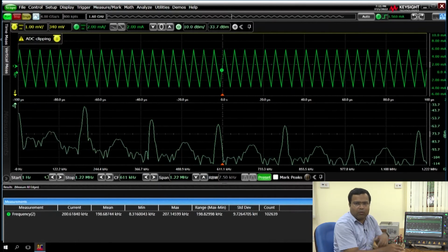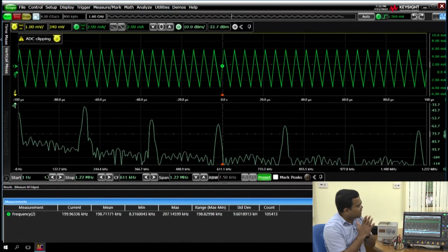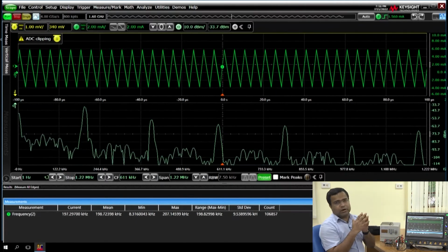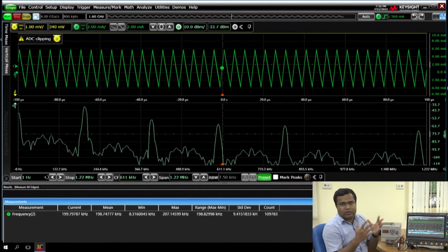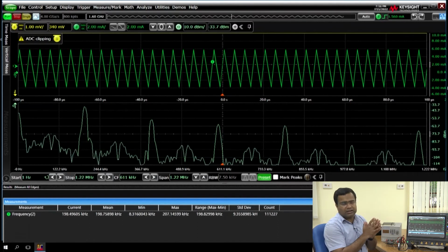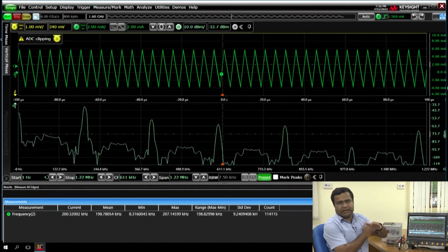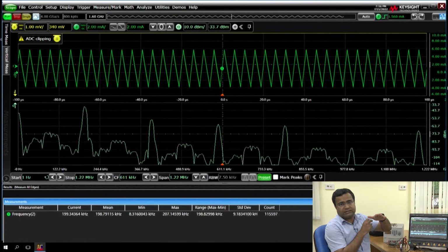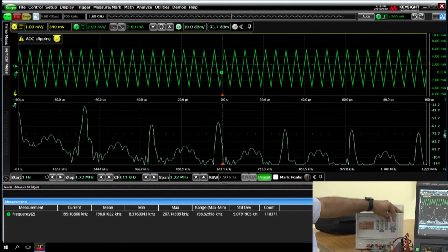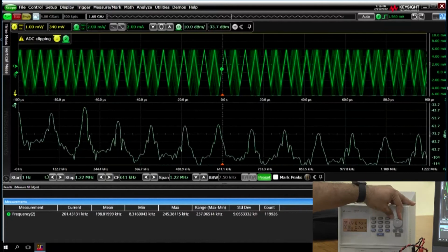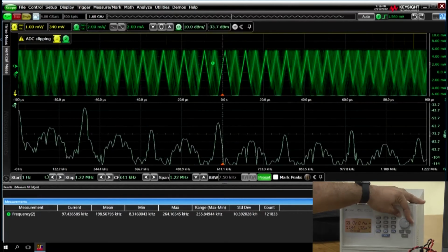Now what will happen if you find instability in the converter, that means cycle by cycle instability? Under this condition, we will discuss the inner current loop stability. If we reduce the input voltage, we already know from our earlier NPTEL course and earlier lectures that the current loop will become unstable if you keep the current reference the same and decrease the input voltage, because then the duty ratio will increase. Let us see, we are decreasing the input voltage, and as a result you can see the duty ratio is changing. Now as we further decrease the input voltage, you can see there is a subharmonic instability.